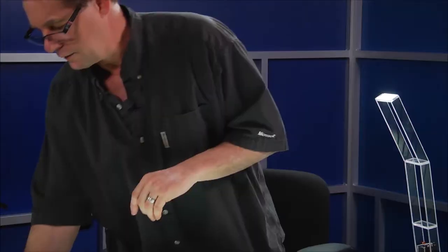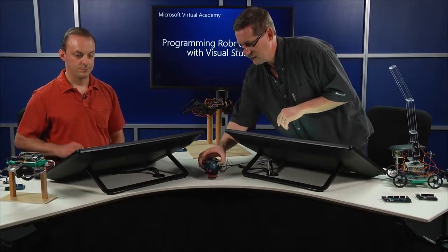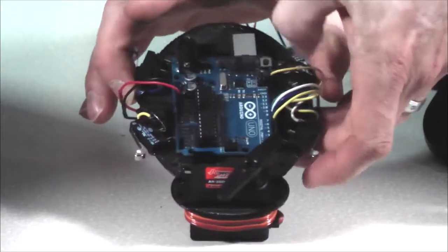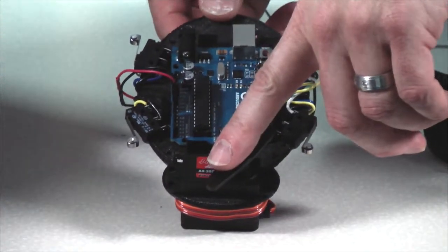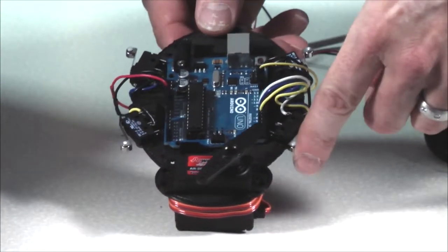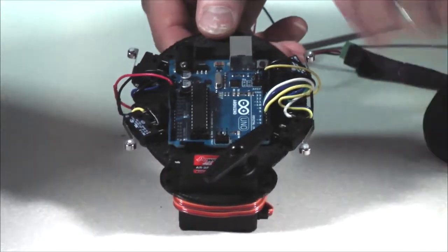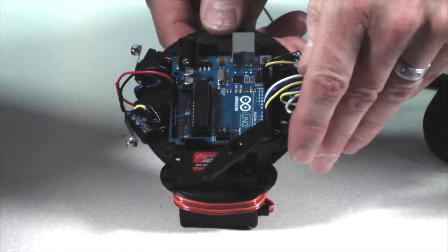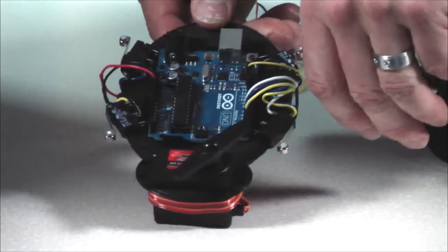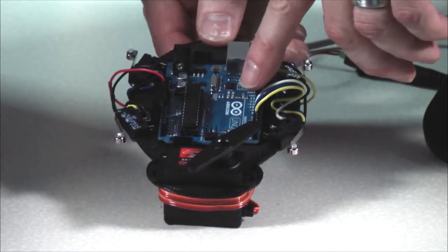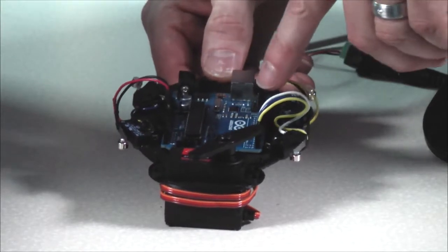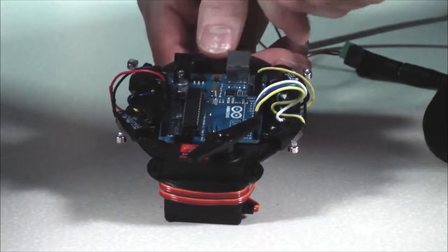All right, so Paul, all I need to do here, so we got this new little guy, right, here. And so he's got the servo in front. That servo's going to run until we touch one of these switches. That should momentarily stop that servo as we touch each one of these. We're wired up to 4 of the digital pins, grounded, and we have a wire for the servo and some power.